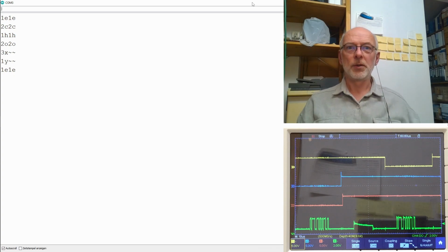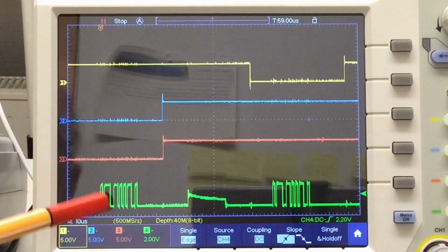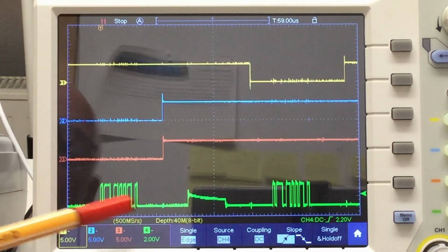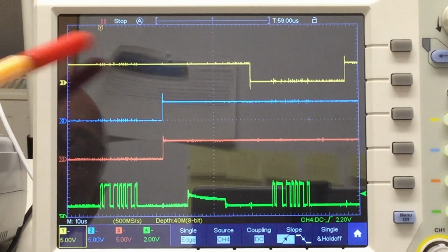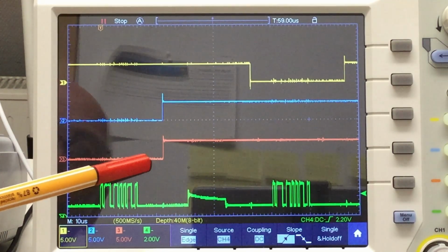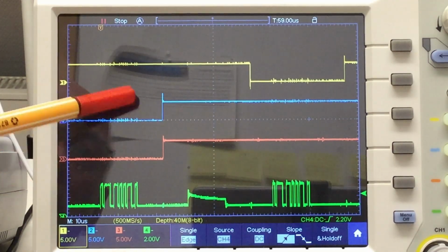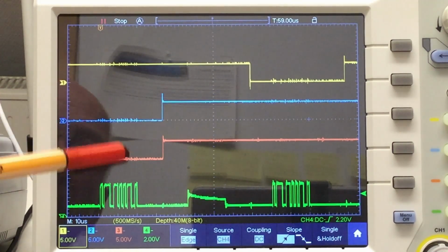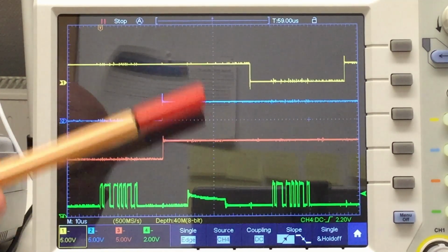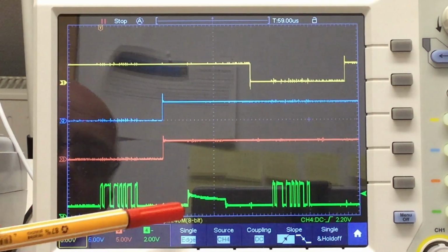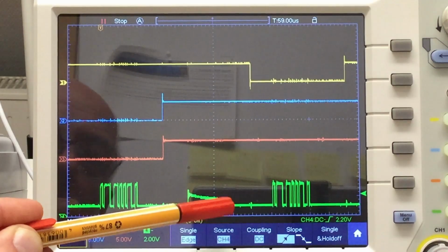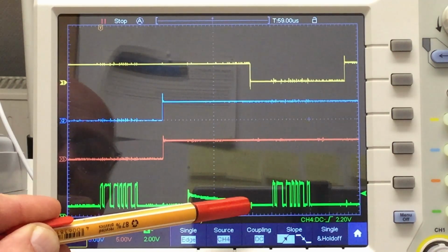Let's have a closer look. We start with the master transferring the message on the bus, which is received by both the first slave and the second slave, after which both disable their receivers. Then our usual protocol dance starts, transferring bus control from the master to the first slave.